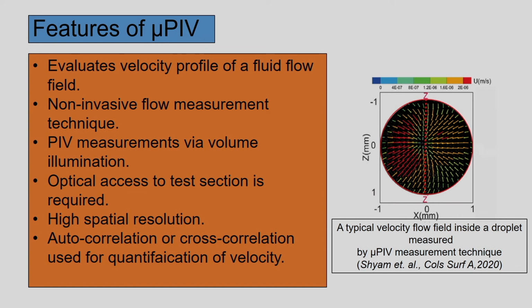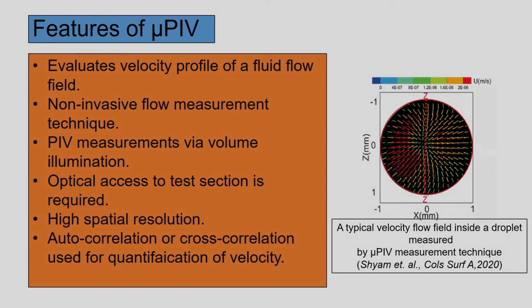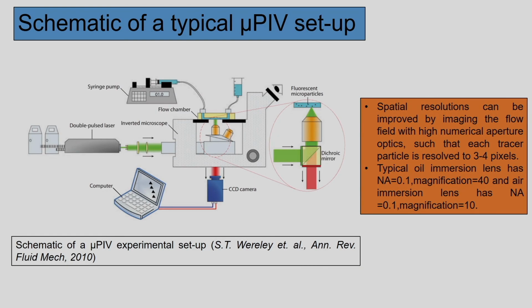Also from the direction of the velocity arrow we can quantify the magnitude. This is possible using this technique, and for that, from the color bar shown at the top of the image we can predict the velocity magnitude. So this method can successfully be used to predict the qualitative as well as quantitative measurement of the flow parameters.